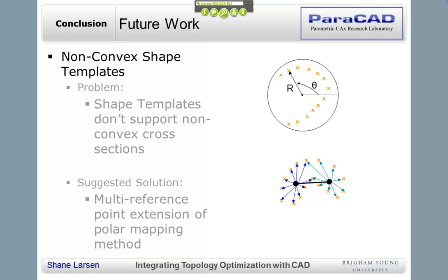Yep. It seems like then after you do the topology optimization, there would still be an amount of testing going on with those dynamic loads, and you still have to do the manual testing. Yeah, so there's lots of tools that will virtually look at thermal issues, virtually look at dynamic issues. There's tools out there that do it, but right now what you're left to kind of come back and adjust are the shape and size parameters of what you build into your parametric model.